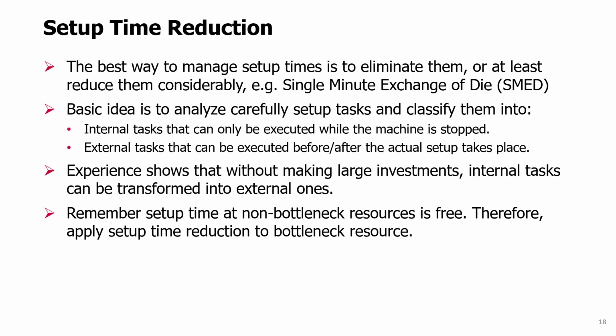Now, the idea of reducing setup time is basically thinking about what are the tasks that are performed during the setup time. Let's break down the setup, disaggregate it and find out if there are any tasks that are internal tasks that must be executed when the machine is stopped, and kind of waste the time of the machine, and make them into external tasks. So tasks that could be done while the machine is processing a batch, we prepare something that will speed up the setup for the next batch.